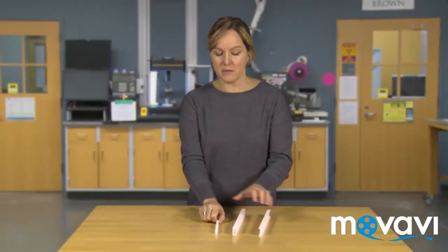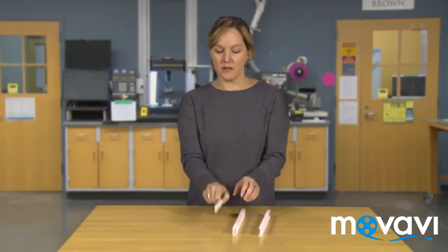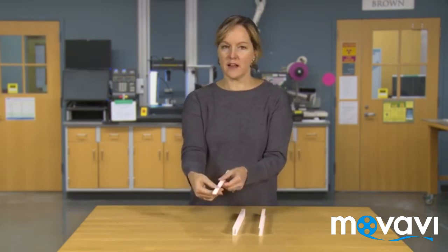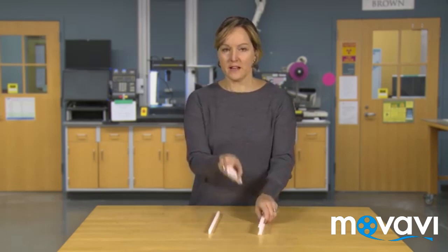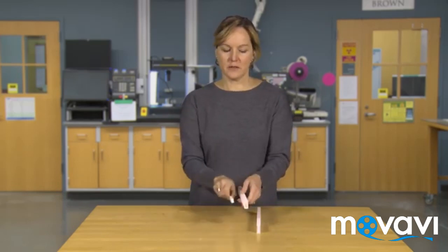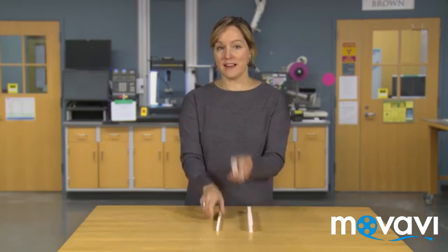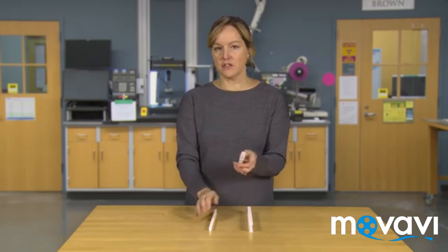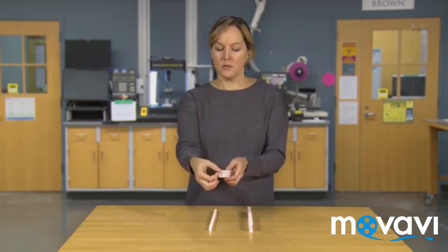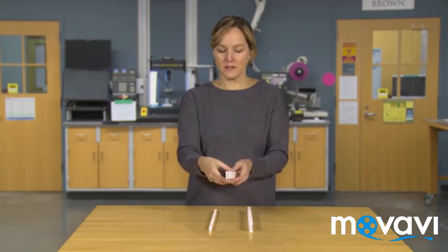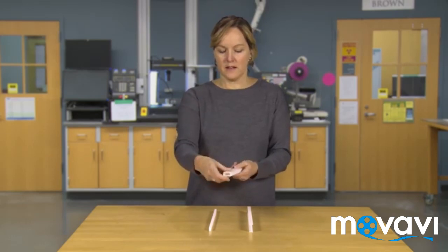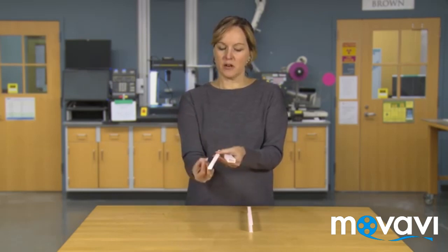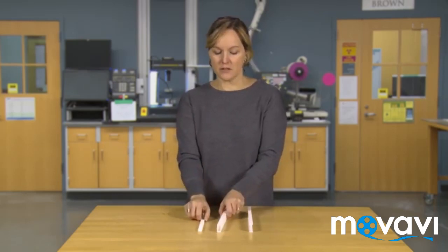We can also look at these 3 different beams. This one is the shorter one, so it's going to have the least moment of inertia. It's also got more of the mass closer to the axis, even if I do it vertically. If I take a hollow section, these were all 3D printed, they all have exactly the same cross-sectional area. So they all use exactly the same amount of material, but they have different shapes. This one is hollow. More of the mass is away from the center, so it's going to end up being stiffer in both directions than the one with all of my mass closer to the central axis. So by taking that same cross-sectional area and moving it away, I tend to make stronger beams.